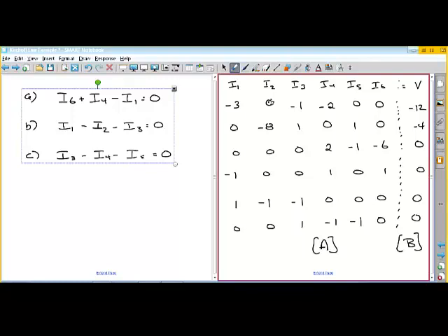So you rearrange them where there is no variable involved, you put a 0, and when there is a coefficient in front of the variable, you put the coefficients. The voltages, the batteries, end up being on the right-hand side of the equation. So basically what we're doing here is taking this A matrix, multiplying by the unknown current matrix, and getting a voltage matrix on the other side.